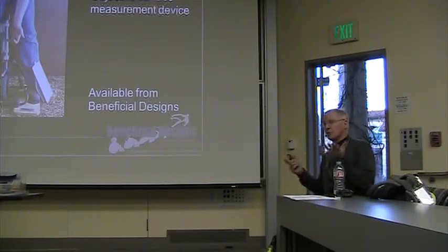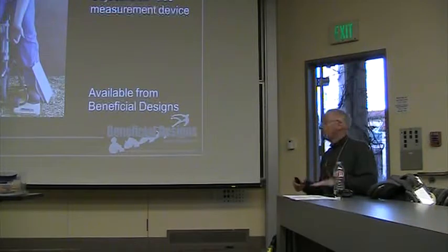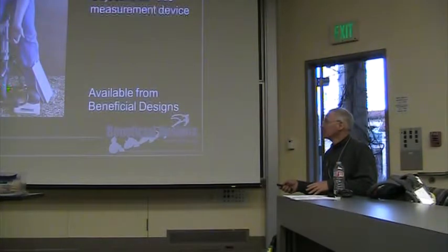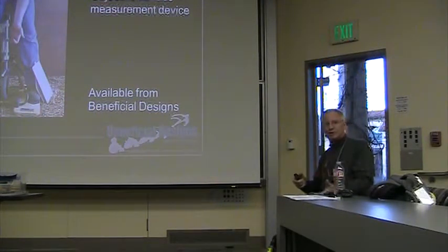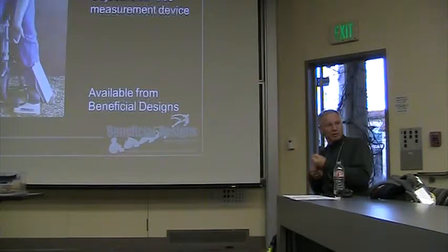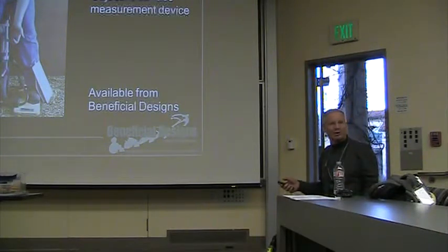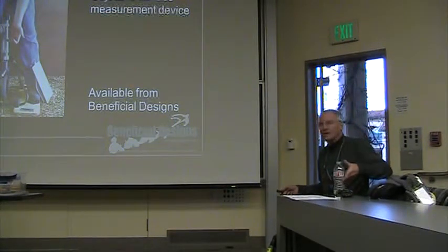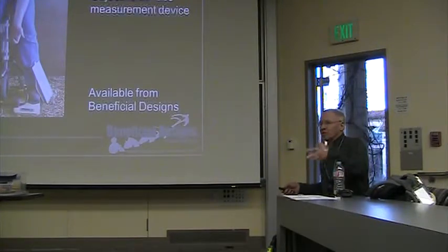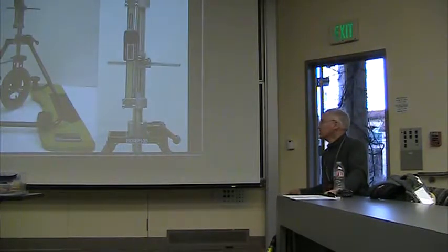So now we've designed a portable device to do that. This is a rotational penetrometer. You stand on it, and it has an indenter, which is an 8-inch wheelchair caster. You set it down on the surface, and then you release the spring. It's a precision spring, and there's a caliper like you'd use in the machine shop right there. It measures how far the indenter goes into the surface, and that's your firmness reading. Then you twist the indenter, and if the surface is unstable, it digs in farther. So then you get the stability reading.